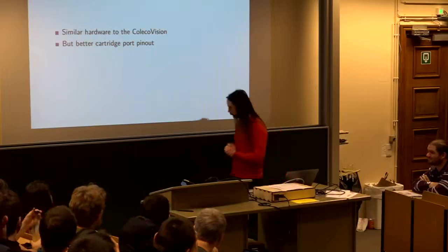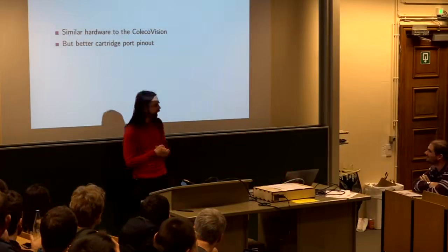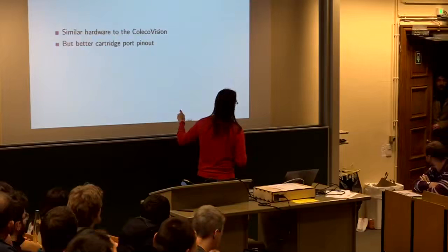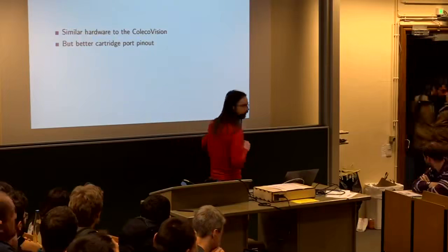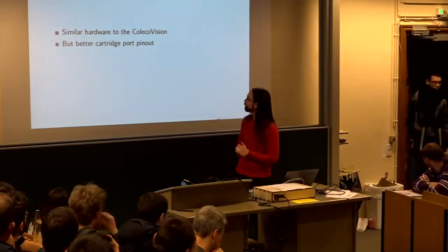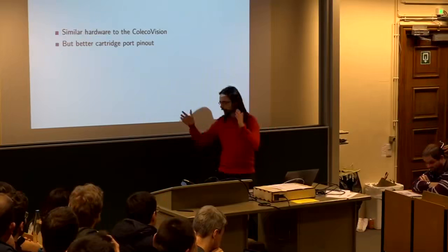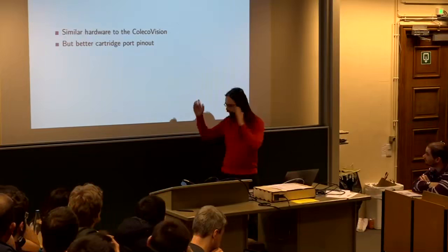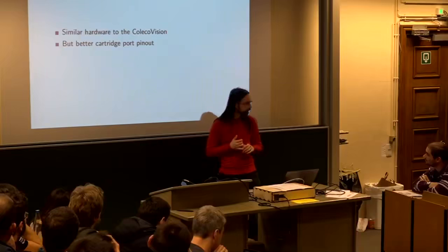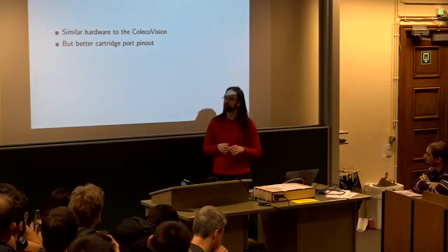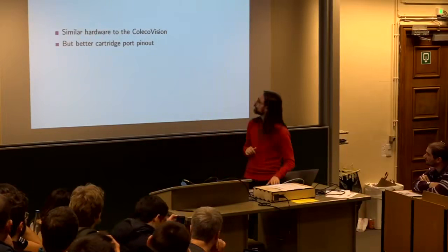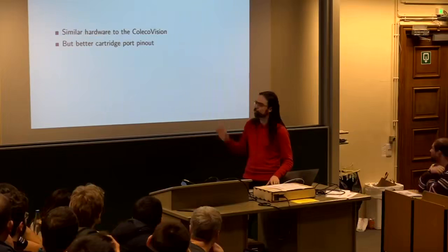Yeah, but there's not just Coleco, there's also Sega, which made something that, if you look at the specifications and the hardware, looks like a clone of the ColecoVision. Their first video game system, the SG-1000, has the same processor, same amount of memory, same graphics chip, same sound chip. Only the cartridge port pin out they did a little bit better. On the other hand, the controllers were, at least on the first model, not detachable but hard soldered to it. They later released a second version with external ports.